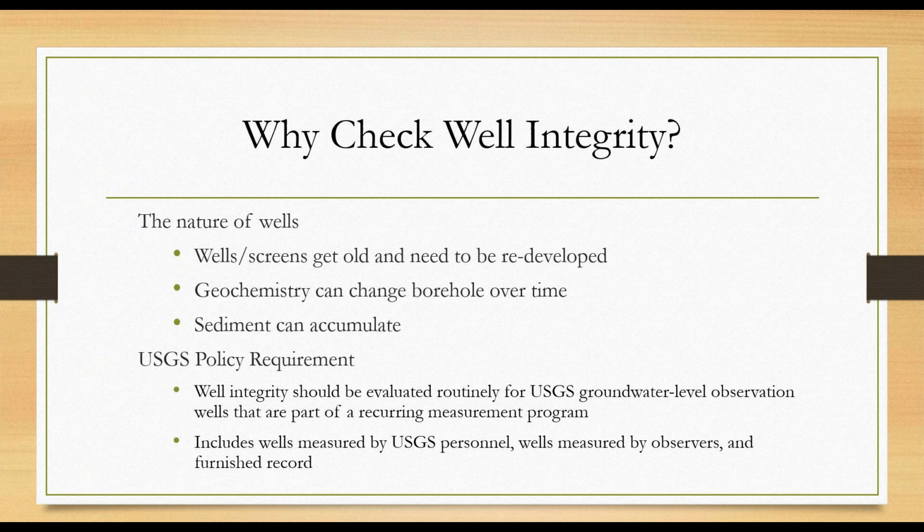So why would we want to check well integrity? I mentioned that we have a policy that states if you have a routine, recurring measurement program, that you will do routine well integrity testing. Because of the nature of wells, we will have wells or screens that get old and need to be redeveloped. And you wouldn't know that unless you really check the connection of that well with the aquifer. Geochemistry can change a borehole over time as well, and sediment can accumulate in the well. This is why we want to check well integrity.